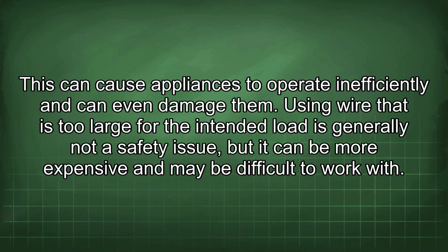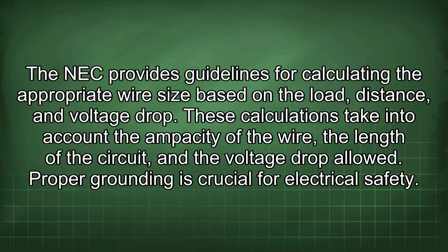Using wire that is too large for the intended load is generally not a safety issue, but it can be more expensive and may be difficult to work with. The NEC provides guidelines for calculating the appropriate wire size based on the load, distance, and voltage drop. These calculations take into account the ampacity of the wire, the length of the circuit, and the voltage drop allowed.